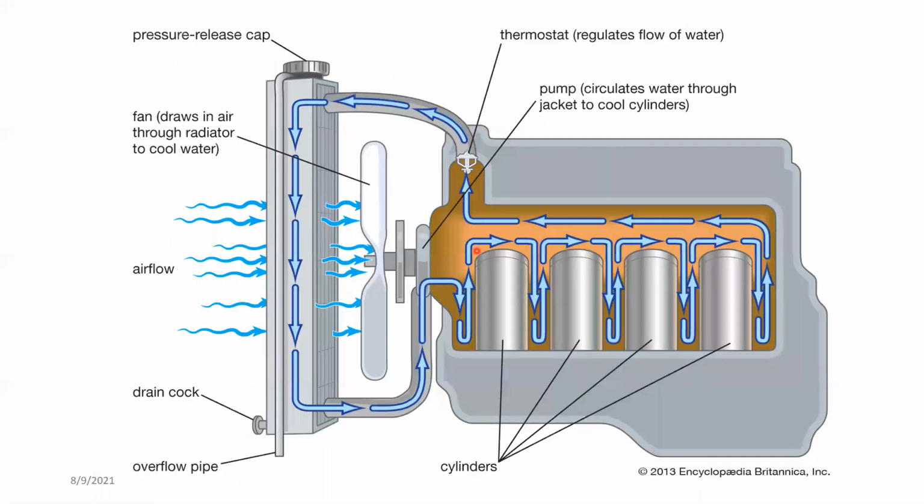So when the temperature increases around the cylinder itself, the water around the cylinder tries to move upwards. When it moves upwards, the water on the top, since it can't go down now, is also pushed upwards. Since this is moving upwards, the water that has cooled at the bottom of the radiator tank comes to take that place, right? It tries to come and take that place.